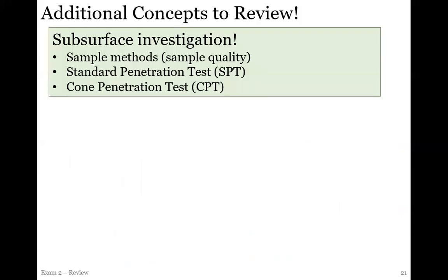The additional concepts, subsurface investigation, this is going to be the heavy concept part. Understanding the sample methods, and then also the standard penetration test and the cone penetration test, the difference between those two. Remember, the big one, standard penetration test, we get a sample. So this is good. For cone penetration test, it's precise, but no sample. So we can't physically do any moisture content tests or anything like that. So know the key differences between those two.